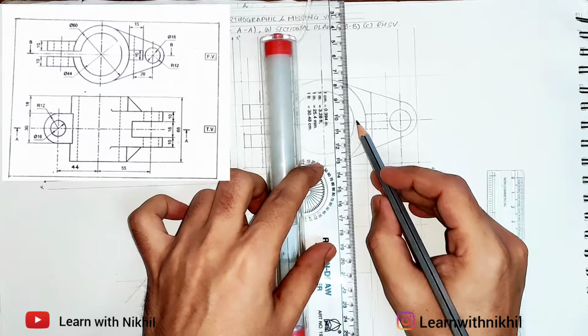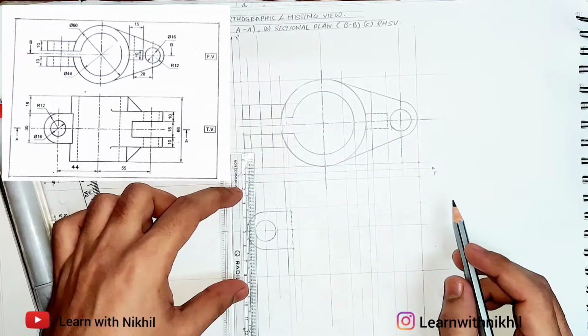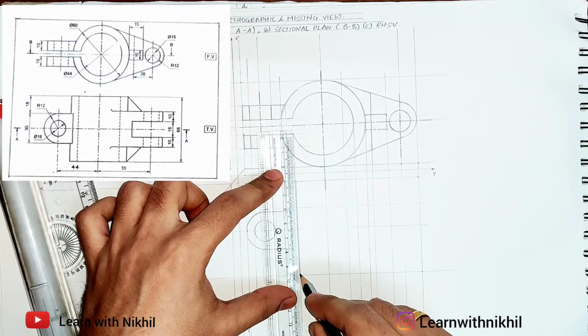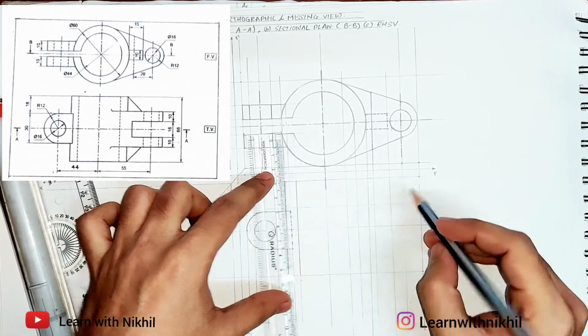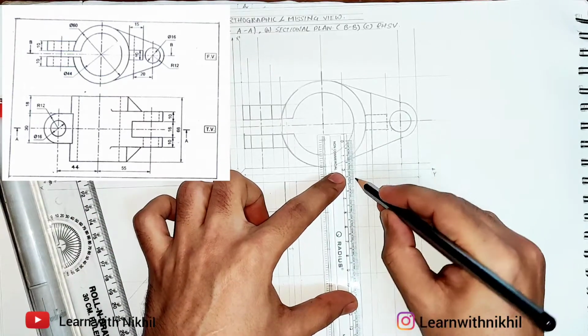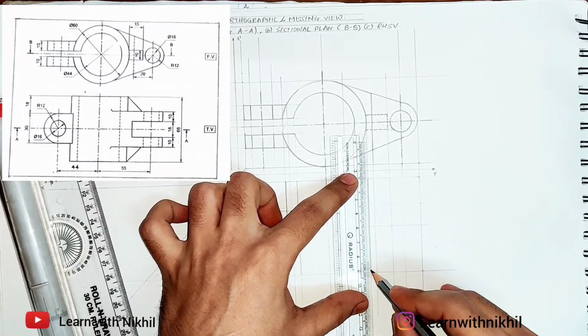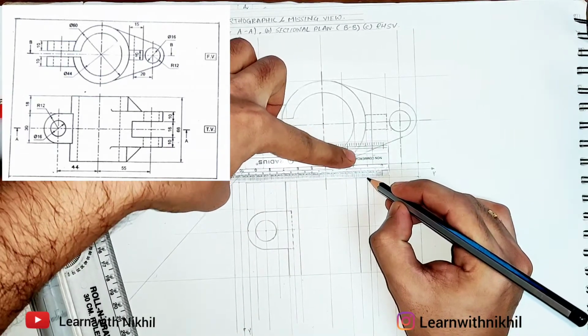Wherever projection lines are remaining, take it downward. This is the inner circle. This will also be dark and visible after the sectioned part. So I'll make this part also dark. This is the outer circle, which is already dark. So this outer circle and the inner circle both will be visible after the sectioned part.